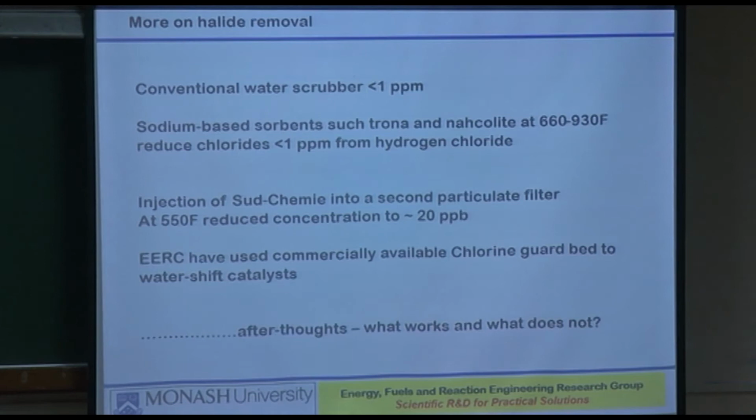The bed material or the wastewater from the scrubber is getting extremely full of chlorine, right? Yes or no? So what do you do with that wastewater? What do you do with that chlorine-rich sorbent bed? Because you can't just throw it down the drain. You have to think about what you will do. Where will that chlorine actually go?